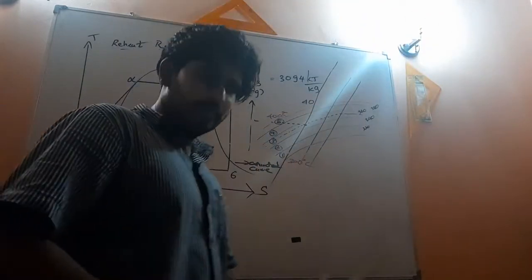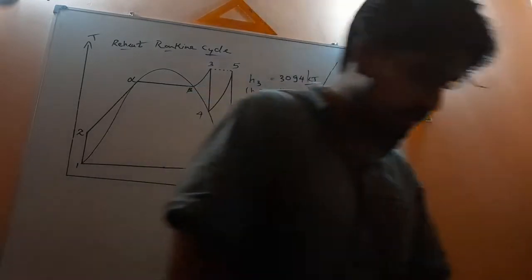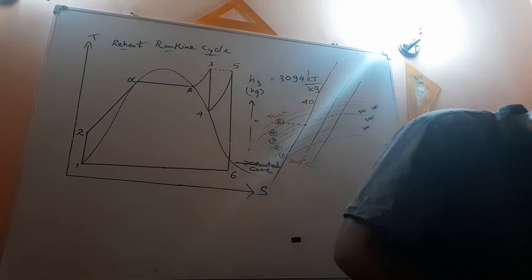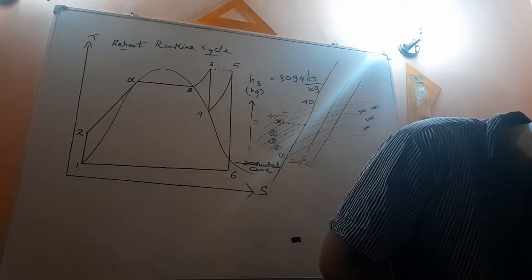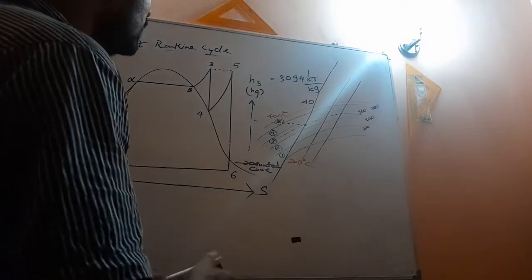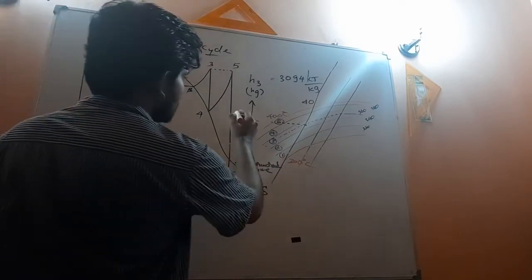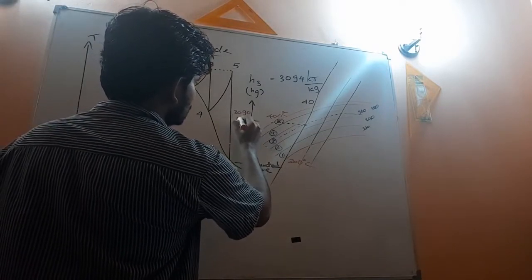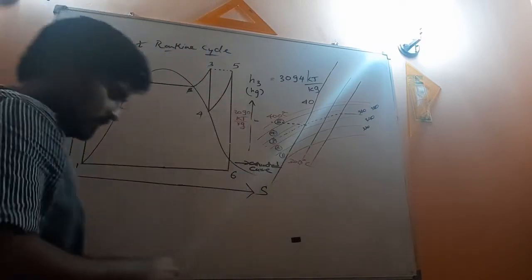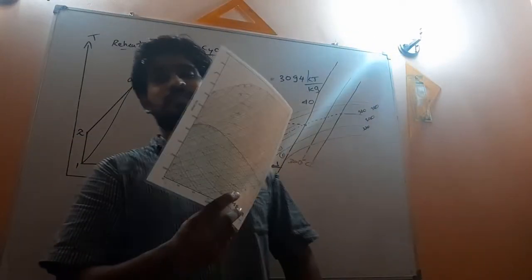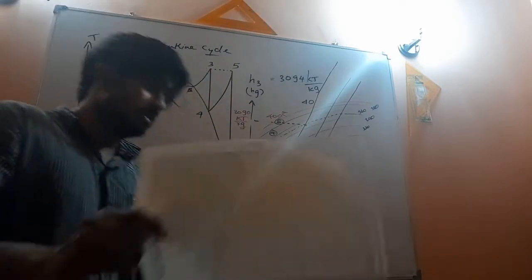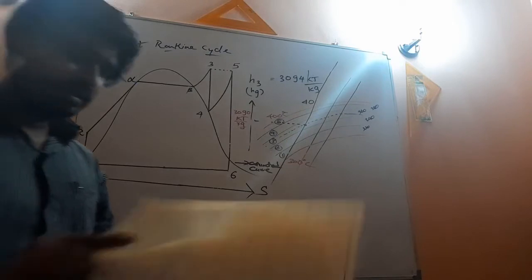So when I read the enthalpy value like that from the HS chart, I got that value as 3090, right? So you guys can also check it, right? So like that I got it as 3090 kilojoules per kilogram, right? Okay, so within this problem I will consider 3090 value because I am going to refer HS chart for that, because otherwise if I am not going to refer HS chart, then I have to use steam tables, then dryness fraction, bit complicated. Okay, right.